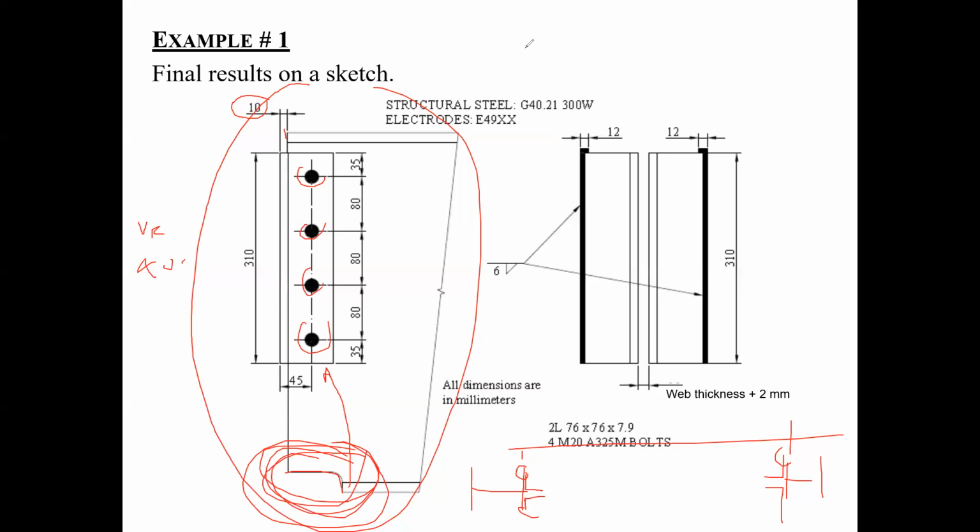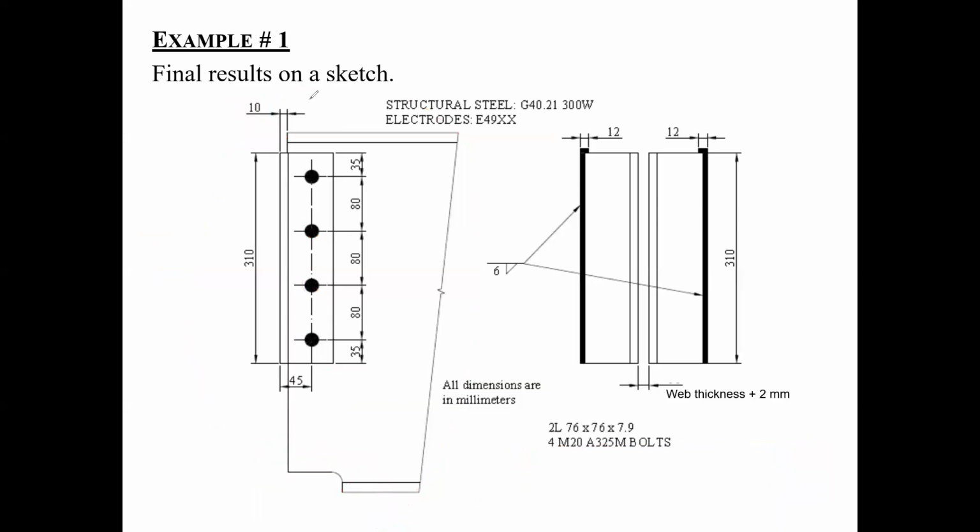And therefore, like I said, this is the coped side of the beam. You cope it so that you can lower the beam in between these two angles. The beam will eventually get lowered in between these two angles like this, and if you do not cut this part of it, you'll never be able to fit it between these two legs, okay?